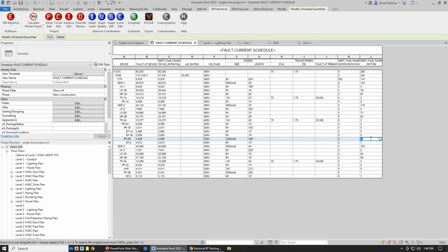So if you specify it as a motor, we're going to include it in the fault calculation, even if it's small. But since the software is, it's kind of built in, the small ones aren't going to matter that much. So it ends up not mattering, which is why you can kind of ignore them on other projects. But with our software, you're just going to get the fault from all of your motors, no matter what size they are. And just know that the small ones are not going to have much of an impact.